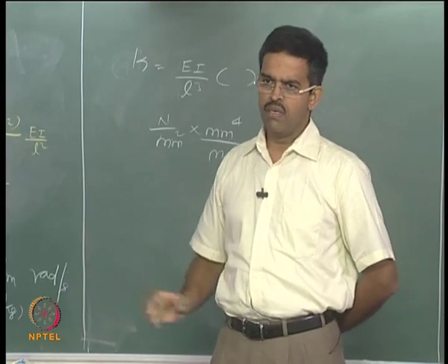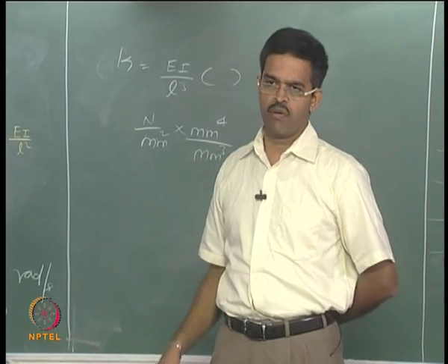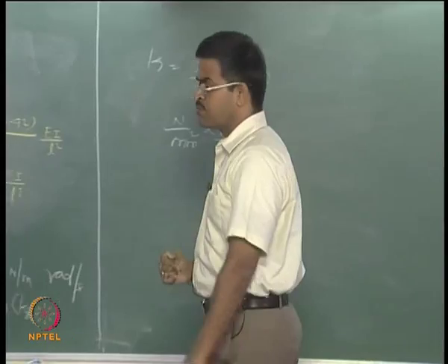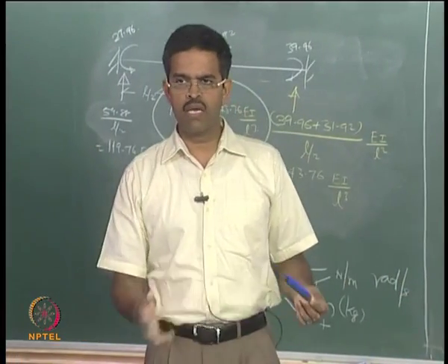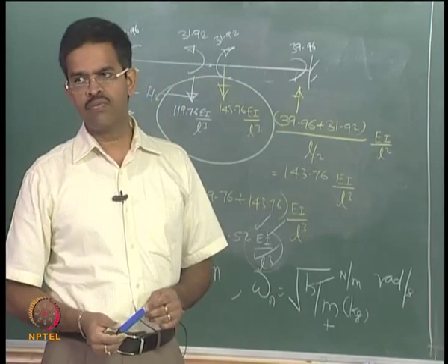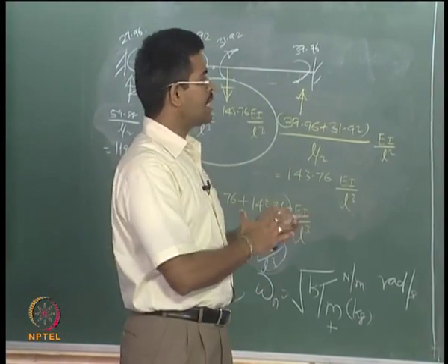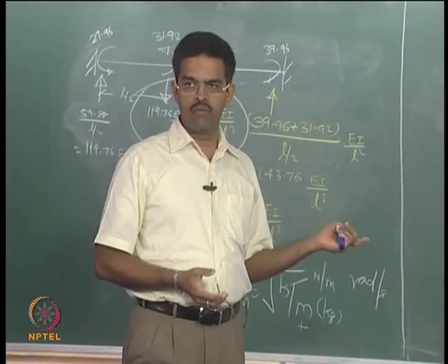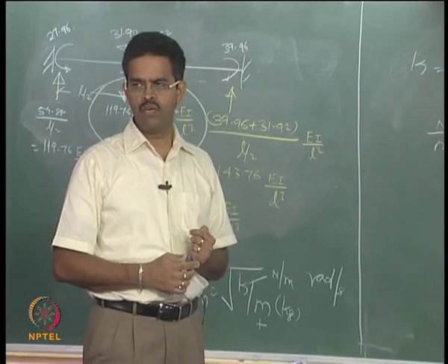It is a very simple classical application of standard structural mechanics for a dynamics problem of single degree. Even in the last example where we saw a truss problem, again the unit load method is a classical example of applying it for a single degree of freedom system for dynamics application. So, for single degree of freedom systems, existing classical theories can be easily applied to find out vibration characteristics or dynamic characteristics of the member.